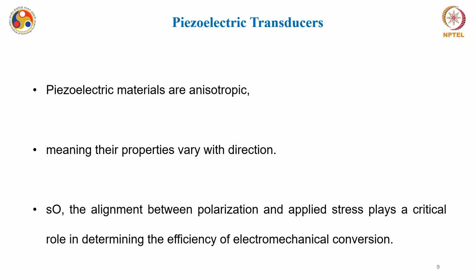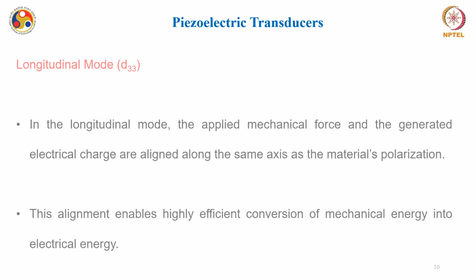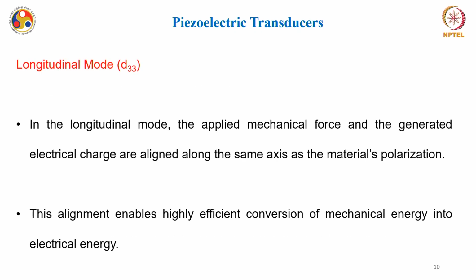So the piezoelectric coefficient may not be the same along, say, the x, y and z directions. They might be different, and that's why you have seen so many different piezoelectric coefficients. The alignment between the polarization and the applied stress plays a critical role in determining the efficiency of the electromechanical conversion of mechanical force into electrical charge.